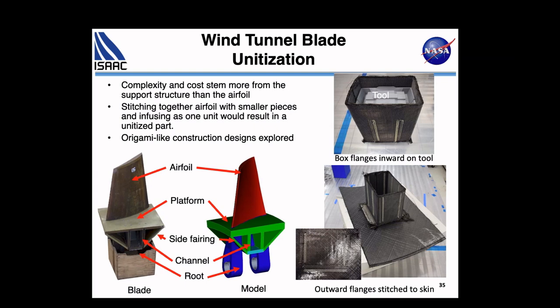And so you've actually got continuous threads, continuous carbon fibers through your part, and it's all put together, and you potentially could build something this complex, including the airfoil, the platform, all the pieces here in just 2 or 3 big parts, and then put them in an oven to cure them.